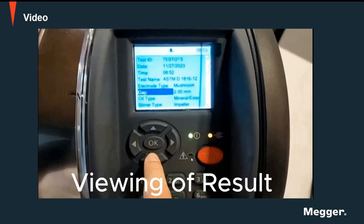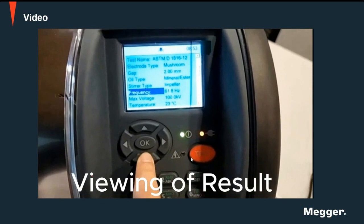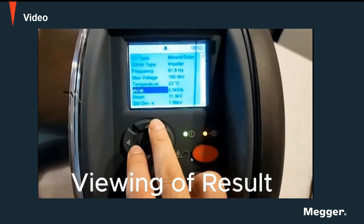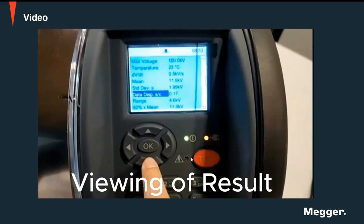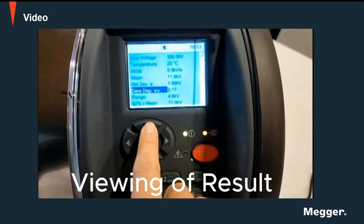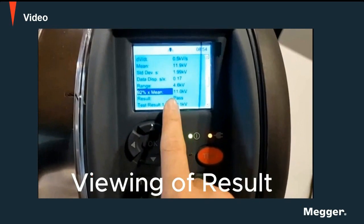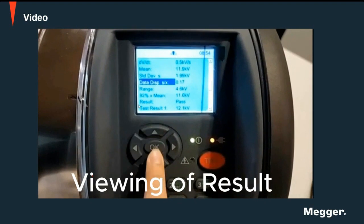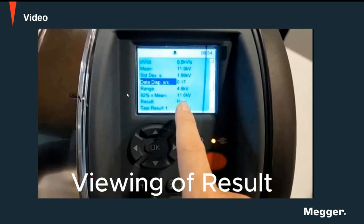You can see the instrument type, the electrode type, the gap used, the oil type, if it is mineral or silicone, stirrer type, the maximum voltage setup, the temperature. Remember, we have this temperature sensor inside. The standard deviation, and the range, that is maximum minus minimum, is 4.6 kV. It's too low. And as you can see, the 92% of the average is 11 kV.